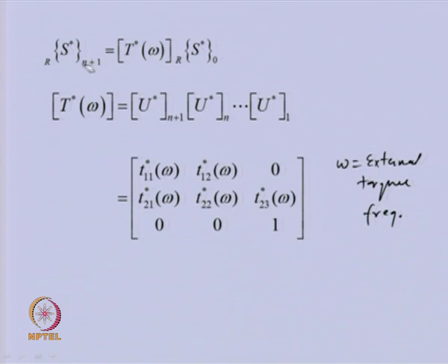That can also be calculated using this particular equation, because this state vector contains not only the angular displacement but also the torque, and depending upon the boundary condition, we can get various angular displacements at various stations. Now, we will take some more examples to illustrate the capability of the method for more complex boundary conditions.